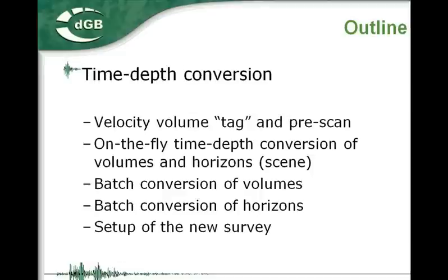And the next theme in this webinar will be time depth conversion, where after looking at a tag we use in OpendTect to help us, we'll see the two main modes in performing time depth conversion. That is the on-the-fly time depth conversion of volumes and horizons through a special OpendTect scene. And we'll go on with the batch conversion of volumes and the batch conversion of horizons. These two are separate, they use different facilities, and we will see how to set up a new survey to use the batch converted data in OpendTect.